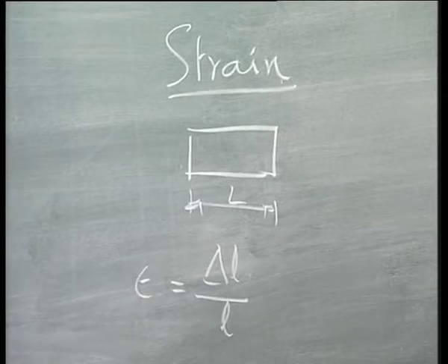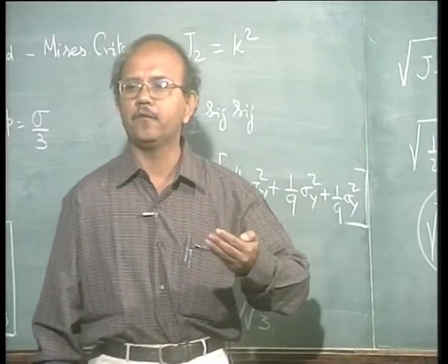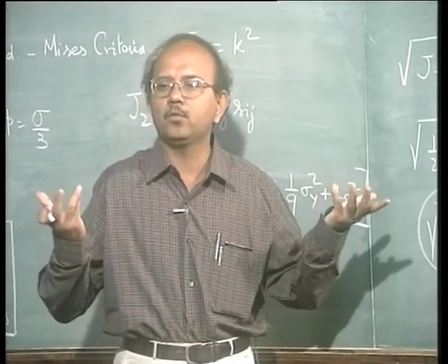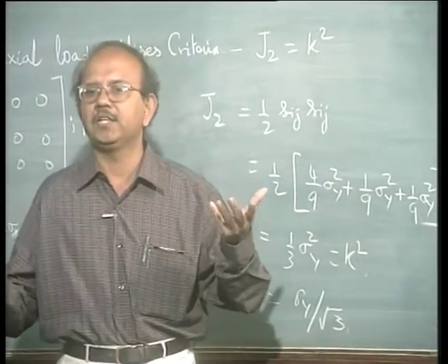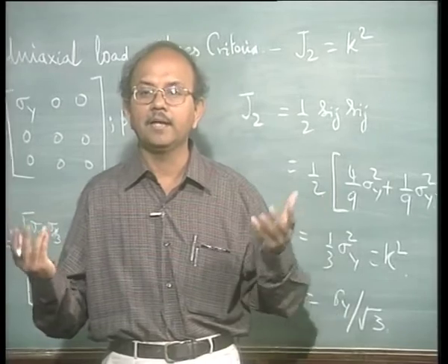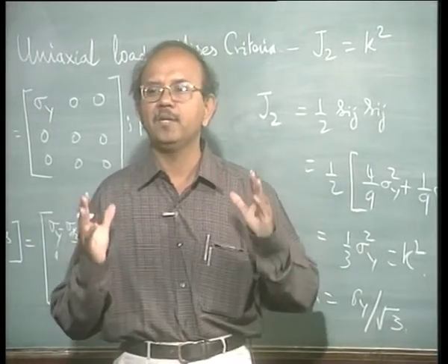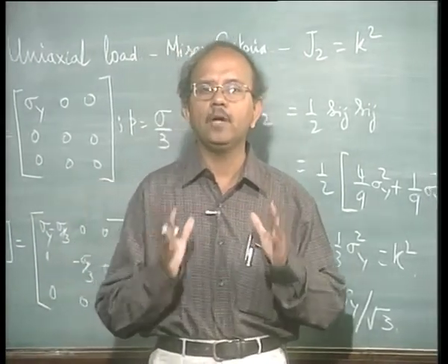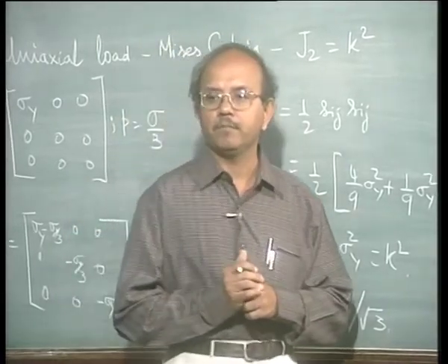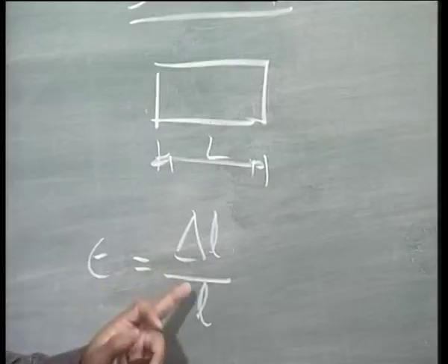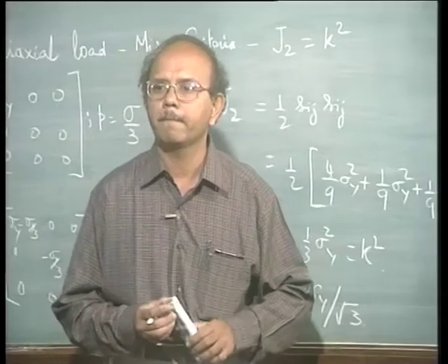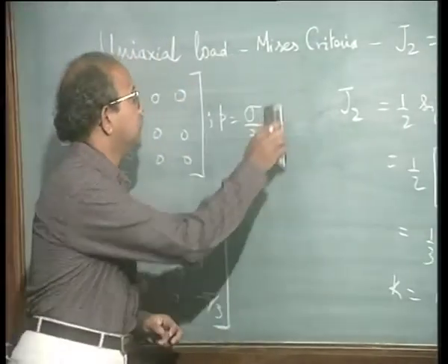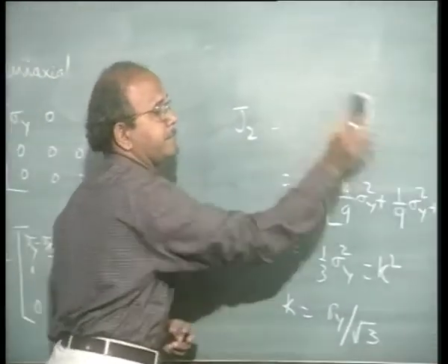Why does that become important? Because I have a body where the strain distribution can be different. So, what is length? There is no length to a 3-dimensional body. I can't define a length to it, okay, and I can't define a change in length to it, and hence my definitions have to be very precise when I go to a 3-dimensional situation. No doubt I will use this kind of relationship, but it would vary as you are going to see now. Okay? We will get back to the definition of strain now.